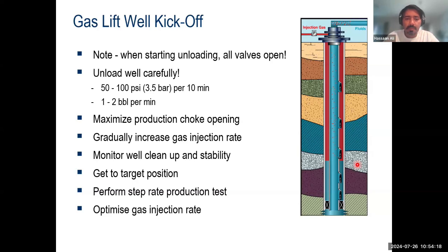In well testing, a well testing crew will come and they will have different types of well testing equipment. They will have separators, different tanks, and flow meters. They will let the well flow under a certain choke setting for a certain period of time. They are trying to determine how much gas is there, how much oil is there, and what the pressures are. So the results from that well testing report will tell you whether you have enough gas in that well for gas lift.